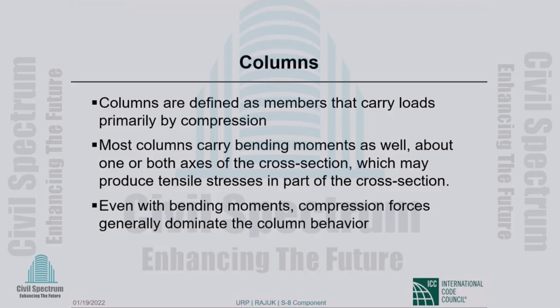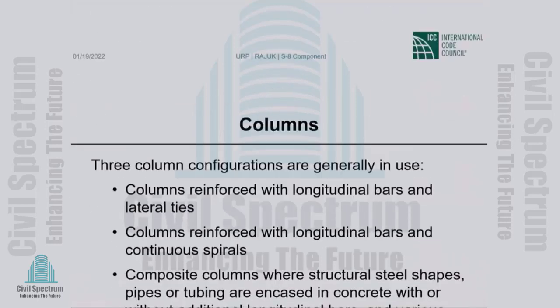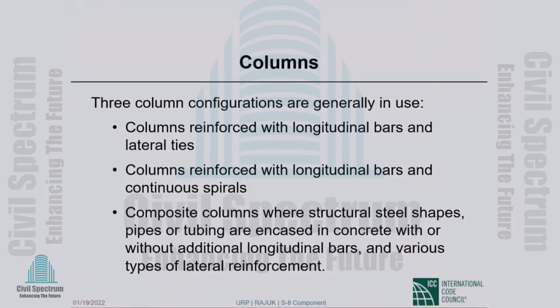Now, even with bending moments, compression forces generally dominate column behavior. That is, again, the key thing that we are talking about, compression-dominated behavior. Not necessarily all the time. There are beam-like columns, with low axial load and high bending moment. In any case, we have in mind compression-dominated members when we talk about columns.